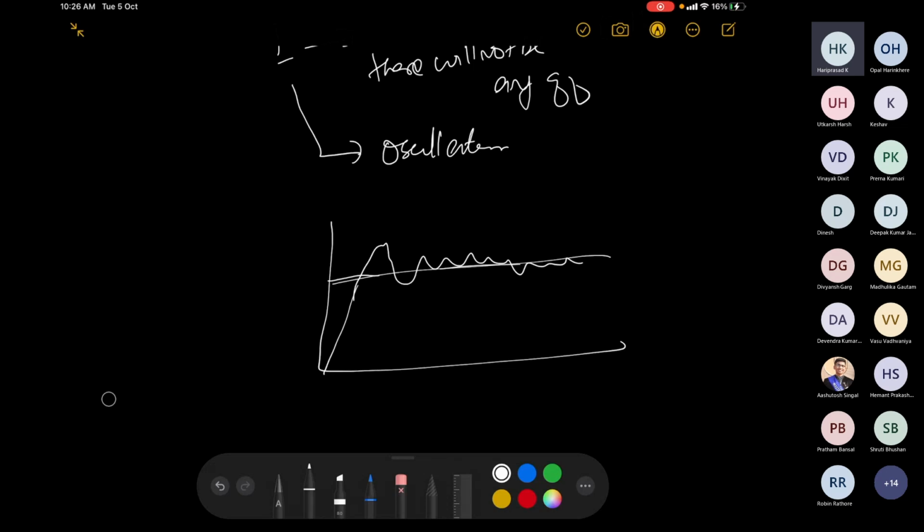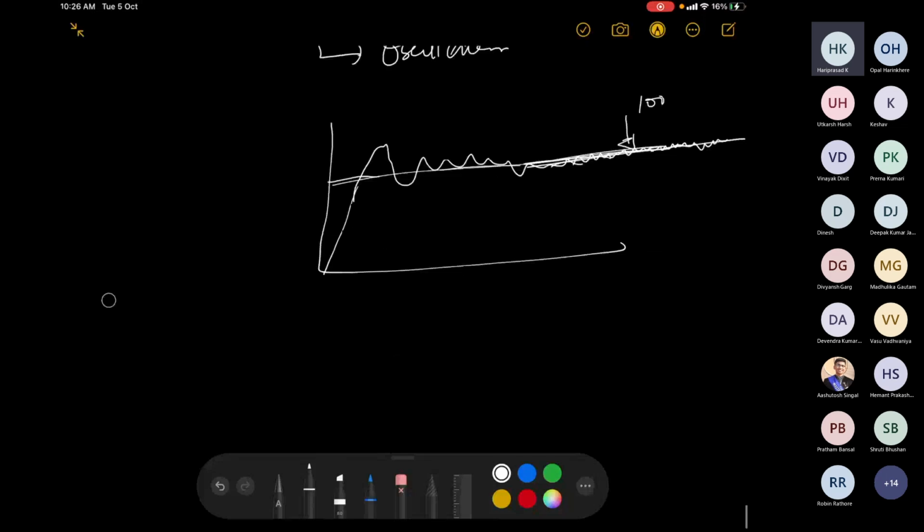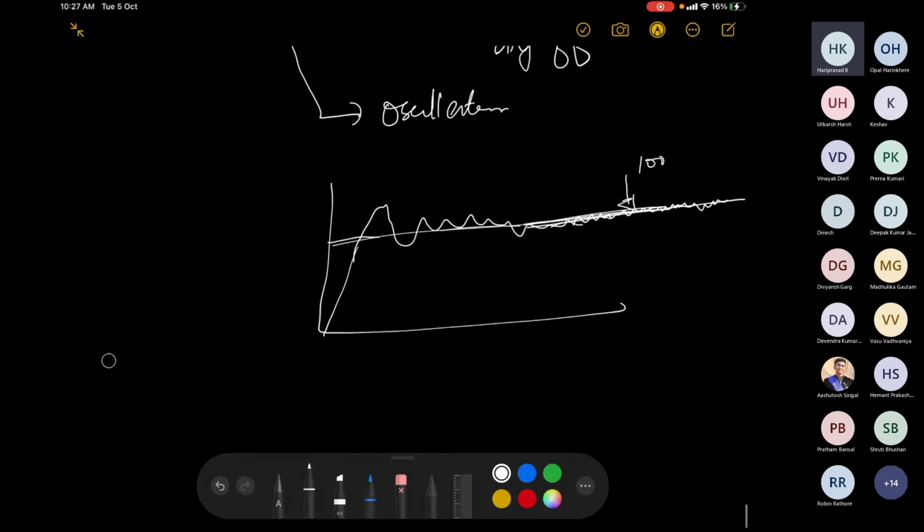Okay. So as a result, you would not reach this set point 100%. You will not be able to lie very close to the set point. What you would really see are some oscillations like this, and when you take the average of this, it would be your set point. Integral action is always active, so there would be some level of control action, and there won't be any offset.